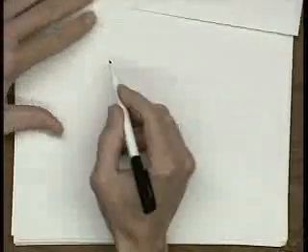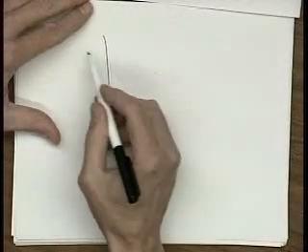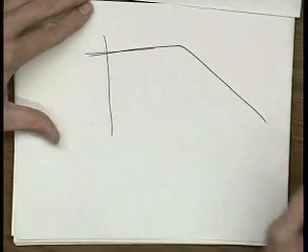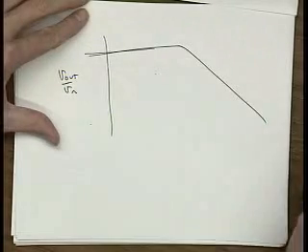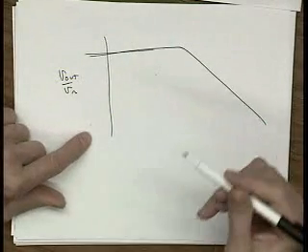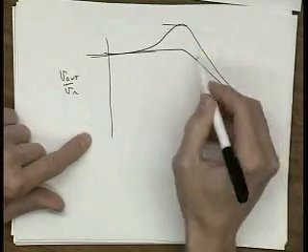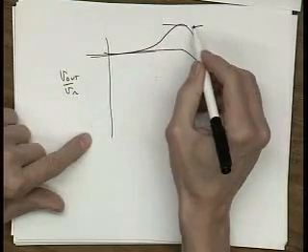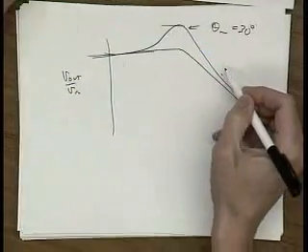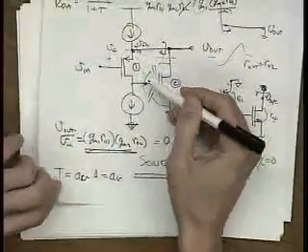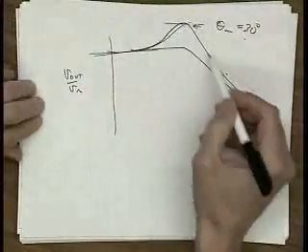Why do we have peaking? What causes peaking? Remember when we did these plots, if you have a circuit like this, this is frequency response of V out over V in. As we have less phase margin, what happens is this circuit will begin to do something like this, right? So as you get to a phase margin of, I don't know, 30 degrees or something like that, you get significant peaking. So this is a feedback network. There's a phase margin associated with it. When the phase margin gets less than, I don't know, 45 or 50, you begin to see some peaking in the frequency response.